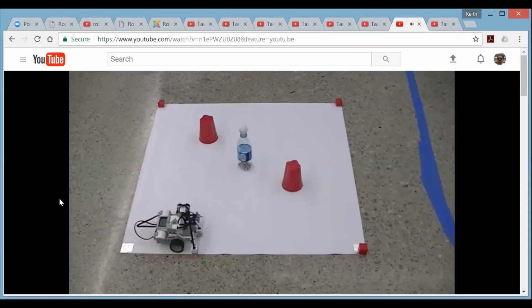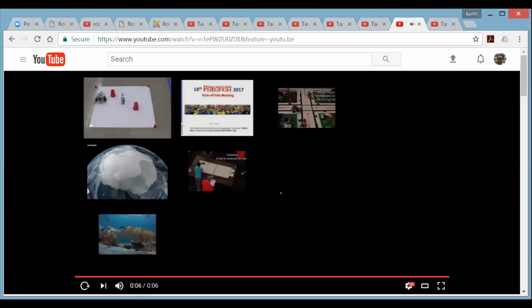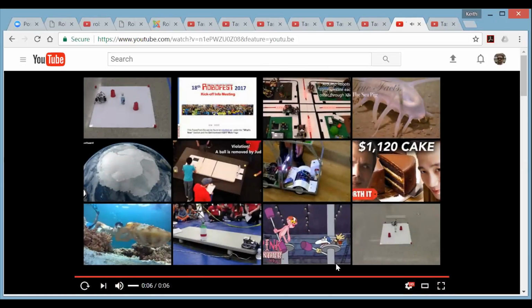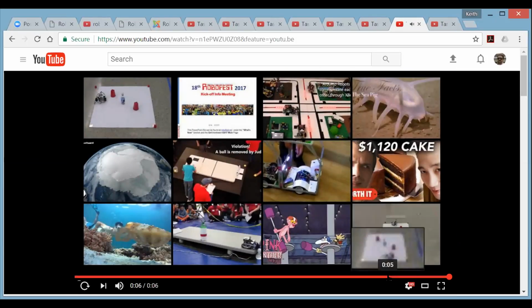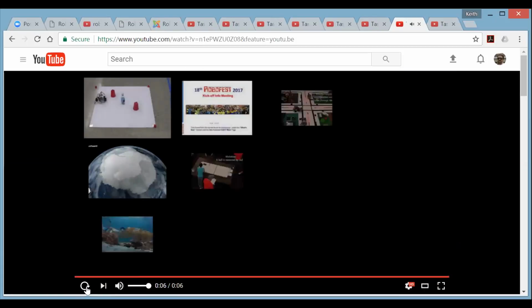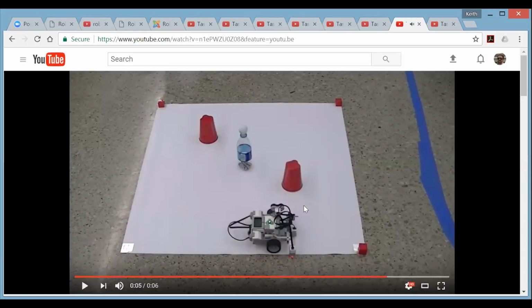Okay, so it travels along, goes past the ball stand, and stops at the cup. Now, let's go back to that and back it up just a smidge. I want to stop something here. Notice that where the ultrasonic sensor is located, it's actually looking behind the cup. Because remember, that cup, it sensed it when it was the edge of that cone that the ultrasonic sensor sees with.